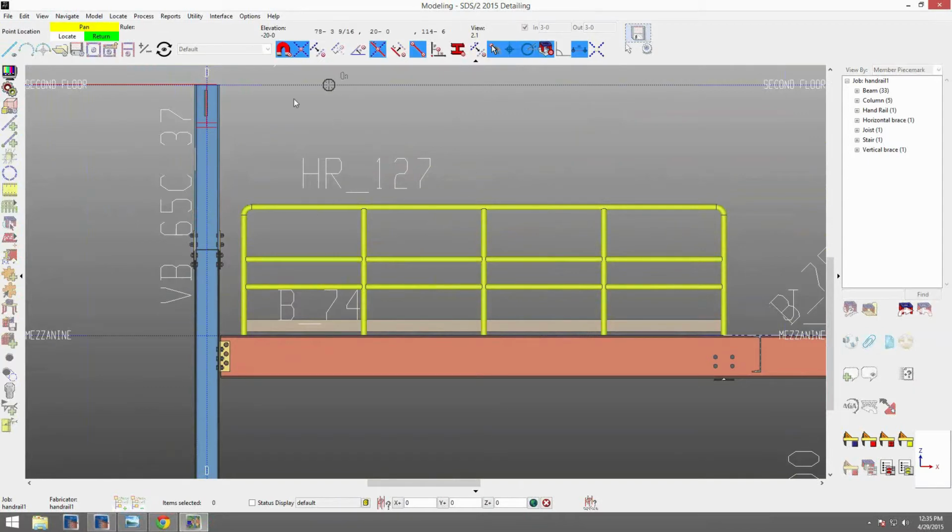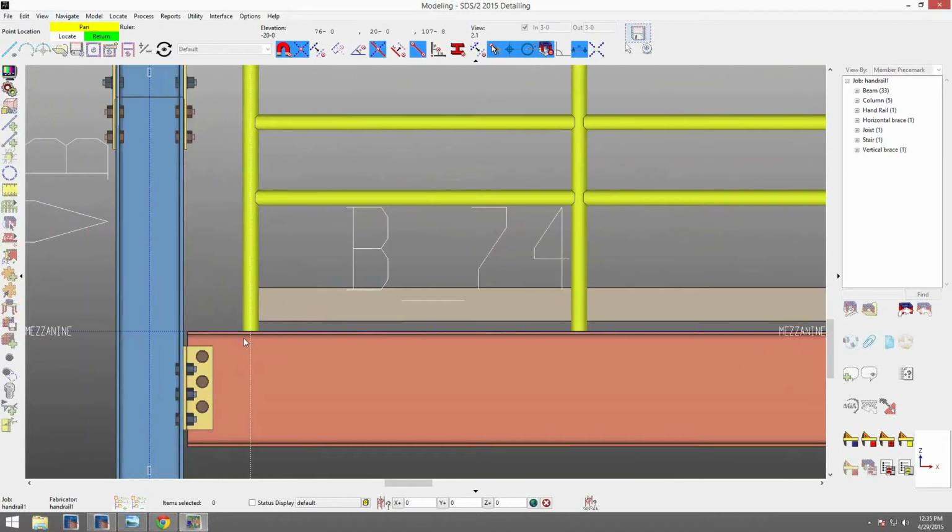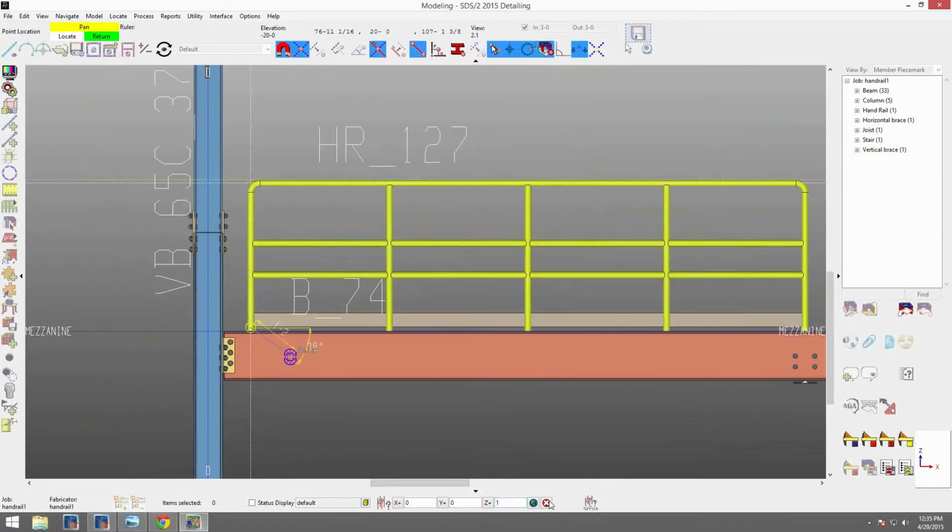Now I'm going to add in construction line add material to show you the dimension here. So if I want to take the dimension, I'm going to come up an inch, so maybe in my z-axis I'll offset this an inch because that would be the top of my floor thickness. And then clear my offsets.